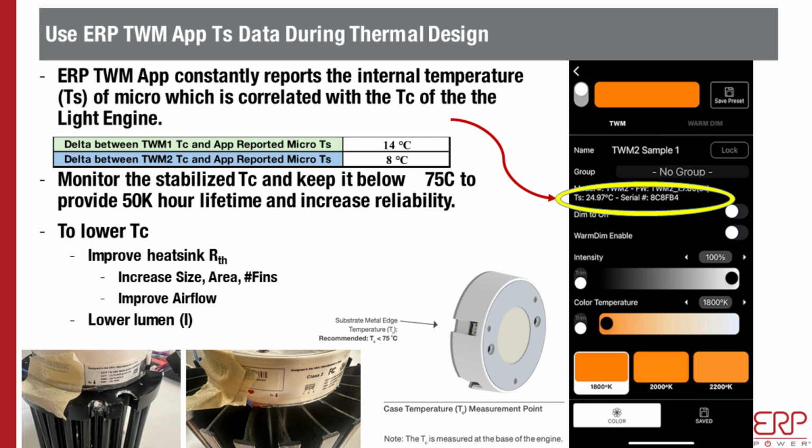So all of these, you can look at the data sheet of the heatsink manufacturer and you can pick up the correct one. Another thing you can do with the existing heatsink is to improve the airflow. And there's a lot of tricks, as I said, spacing them out, drilling holes, and there's also all sorts of other tricks you can do.